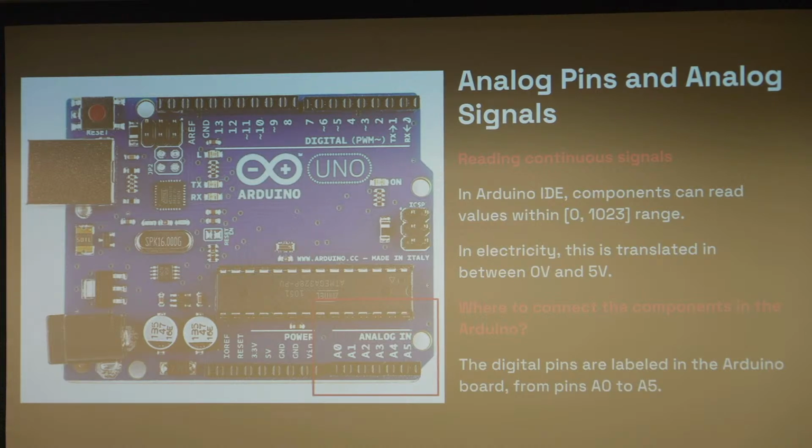If you want to handle output with a continuous range, as we did in the previous one, we're going to be using PWM, which is a special case for digital signaling. I think I made a mistake. Actually, it's not for output. We're not going to be doing it with LEDs, but you're going to be using it as input with the analog, anything between 0 and 1023.